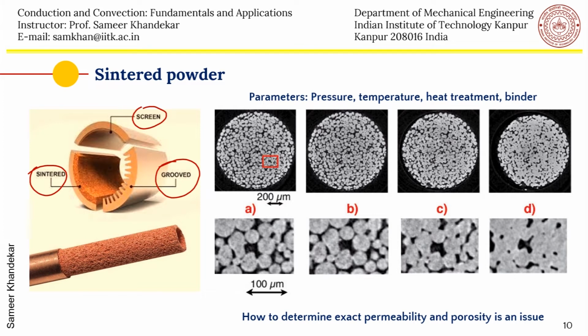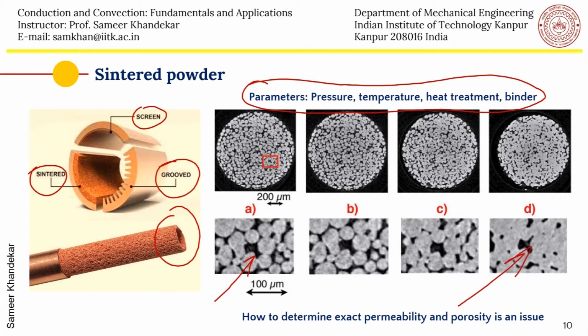So depending on the temperature and the time, you can see the porosity is getting lowered as you go in this direction. Initially you can see the particles, then slowly they fuse with each other, and more and more heat will make the fusion closer and stronger, and there will be plastic deformation because we are giving a pressure when the heat is being applied and the wick is being formed. Then slowly, depending on these particular parameters of powder metallurgy control, we will be able to get the desired porosity and the desired permeability.